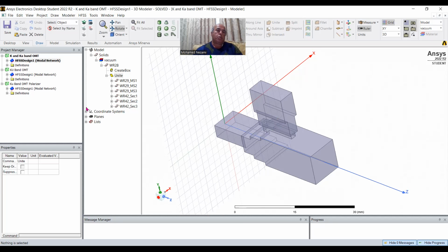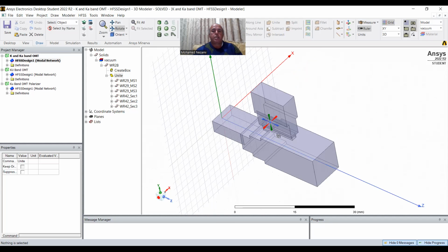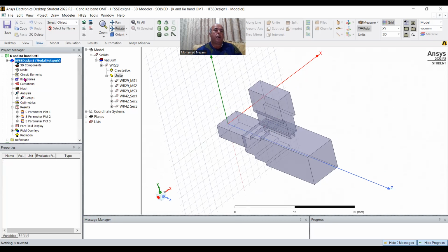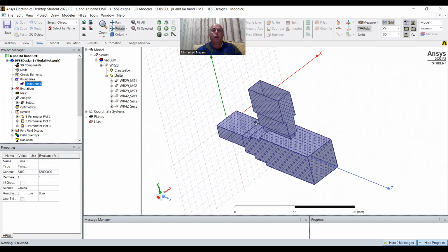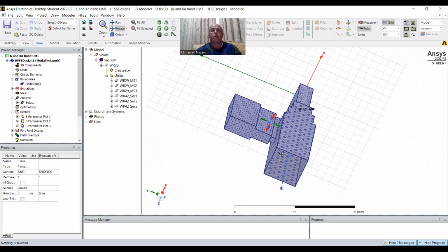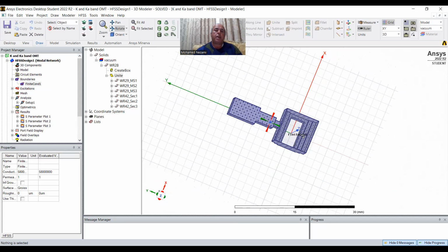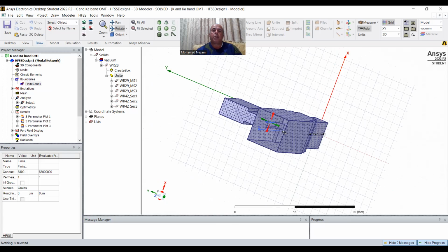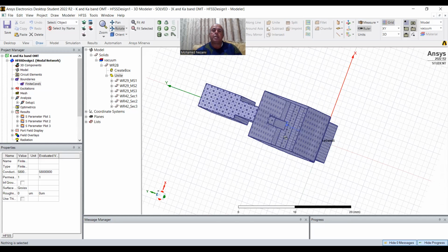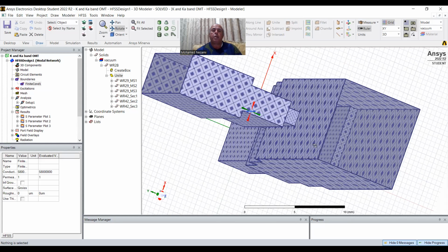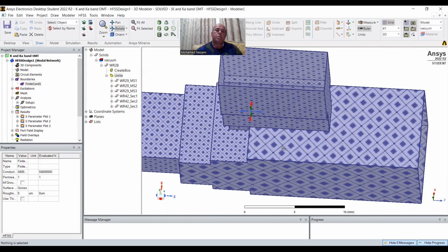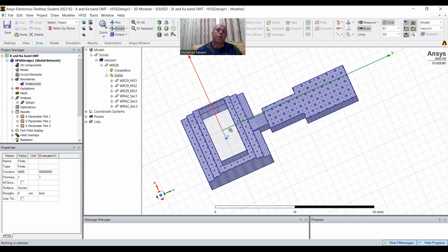So in my case, because of simulations, what I did is I said, okay, let's make it all air, and let's come in here and define a boundary of the whole thing as a perfect conductor from the outside, as you can see in here. Okay, so it is basically, you got the opening is here. Okay, for this one here, for this side, and there's the opening for this side for that one.